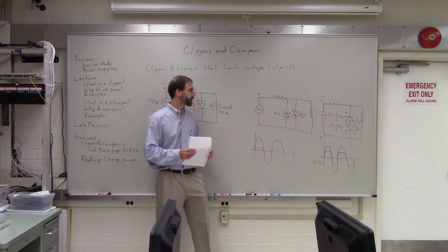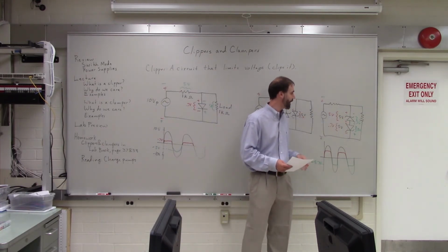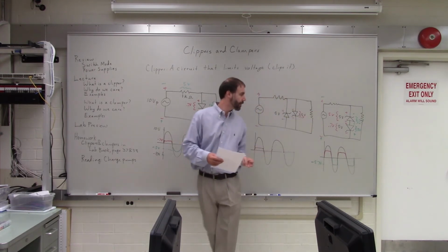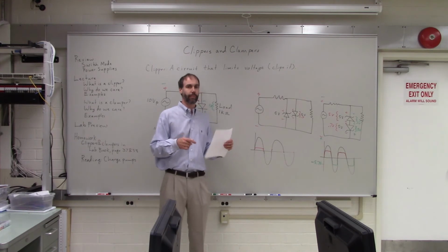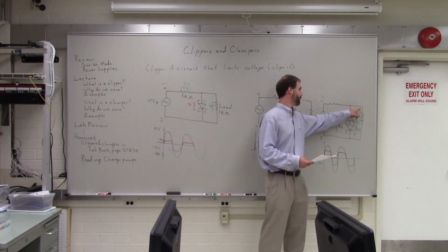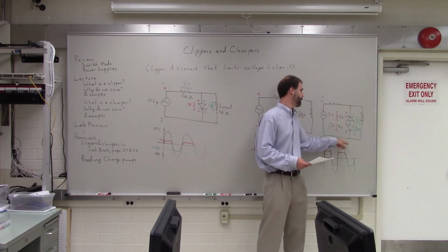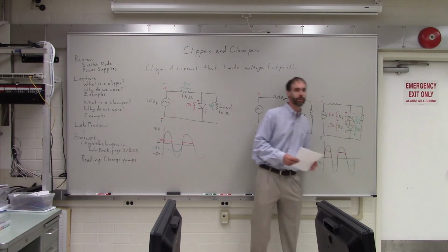Also like protection. Exactly. So you put a pair of diodes like this back to back, a pair of Zener diodes, and then that limits the maximum voltage that can happen. So when the motor tries to spike up, that extra energy just loops around through here and goes around in a big circle and wears itself out.